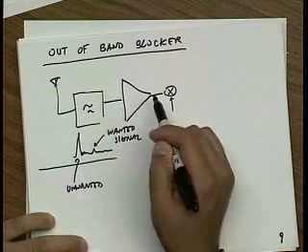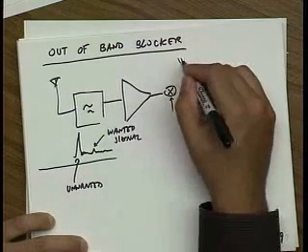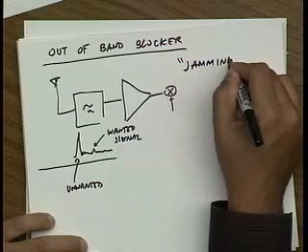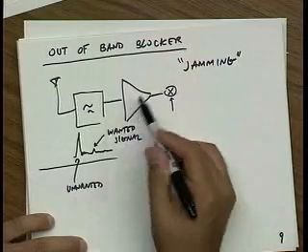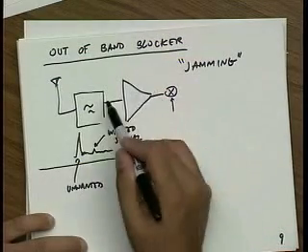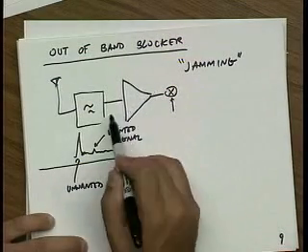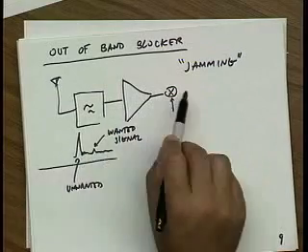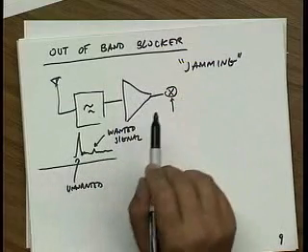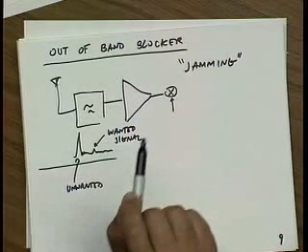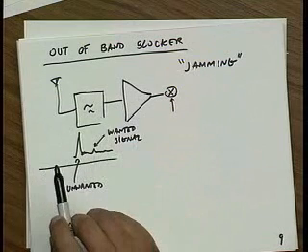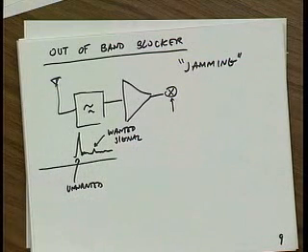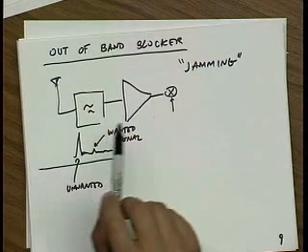If you have nonlinearity, what you do is you get jamming. The concept of jamming is that this big tone reduces the gain of this amplifier so that the small tone sees less gain. In fact, what we'll do is we'll calculate when the apparent gain of this amplifier is dropped by 3 dB. And we'll find that power level, we'll call that power level the 3 dB out-of-band blocker power level. But forget the terminology. It's more important to figure out the concept here.